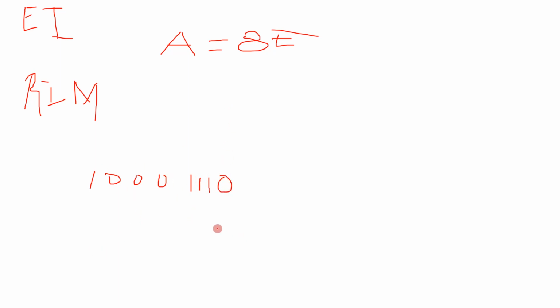We'll get this. So this bit will be serially input from the serial interface. This will be the input. The RIM instruction will read the input through the pin SID. This, and this, indicates these two bits. This is for 6.5, this is for 5.5, and this is for 7.5 interrupt.